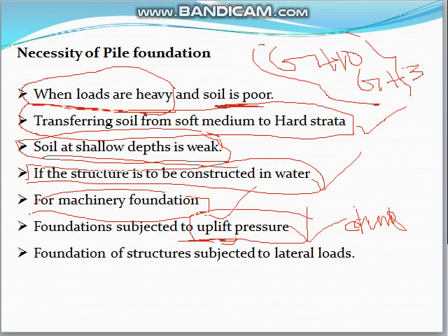Another one: foundations or structures subjected to lateral loads. Generally, lateral loads are the loads acting on the superstructure, so for that also pile foundation will be preferred. So these are the main necessities of the pile foundation.